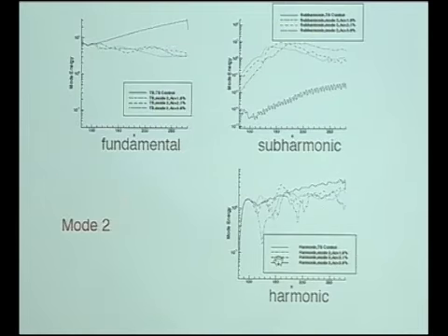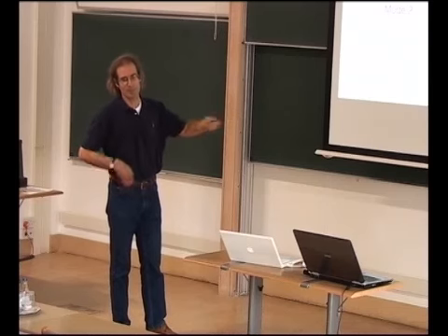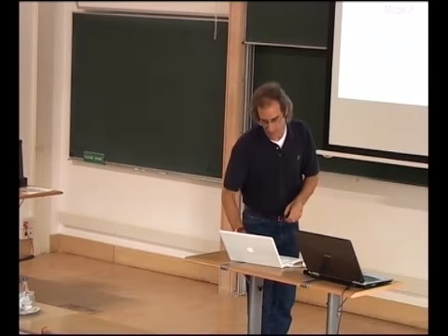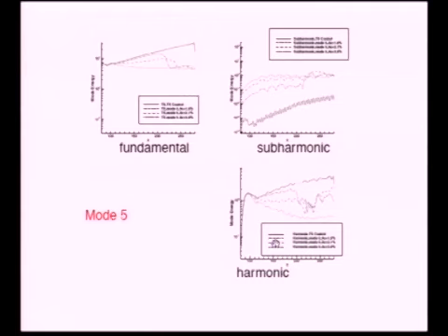In this case, you see the subharmonic growing, and there seems to be an instability that involves the subharmonic growing, whereas the harmonic is not very much affected by the interaction. So it suppresses this, but causes a secondary instability. And where transition takes place is a competition between the Tollmien-Schlichting wave growth being suppressed and the secondary instability taking over. So if the continuous mode is very strong, it will kill off the Tollmien-Schlichting wave, and you won't get transition, or it will delay transition.